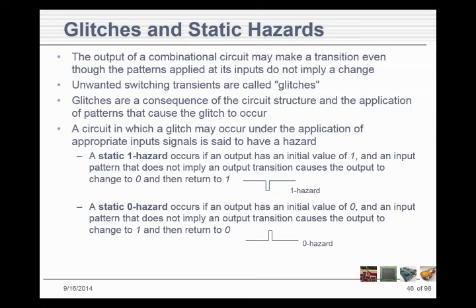But you need the personality modules for the processor you're working with. Otherwise, all you've got is all the lines, and then you've got to do a lot more of that in your head. I mean, I can look at the address lines for a while and the data lines for a while, and after a little while, I can start picking up what they should be and do some troubleshooting.